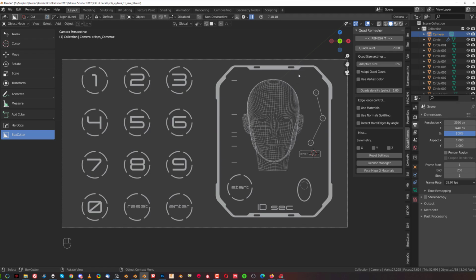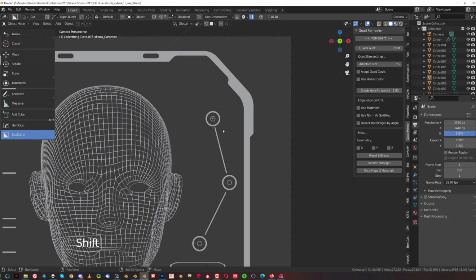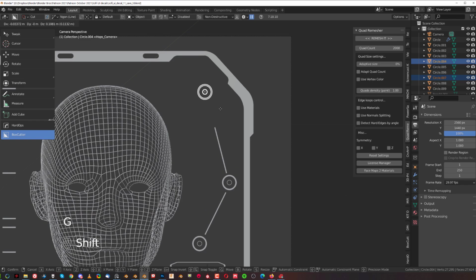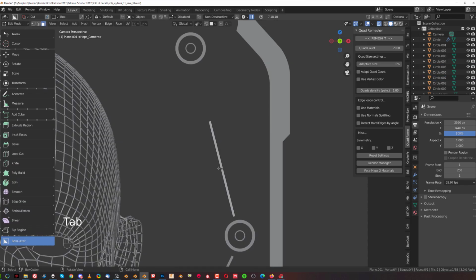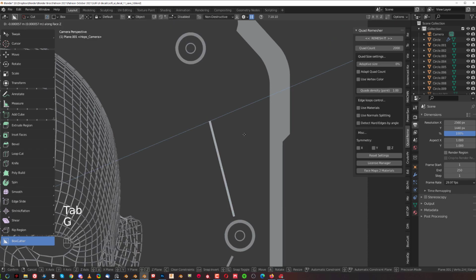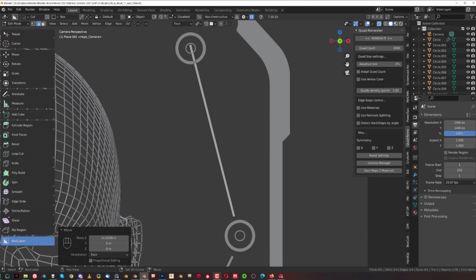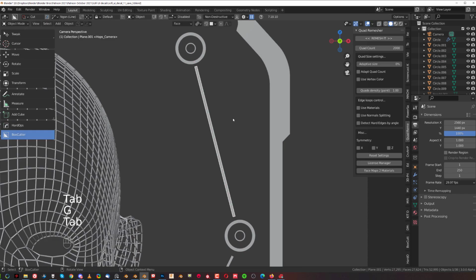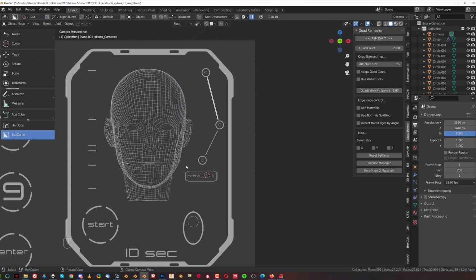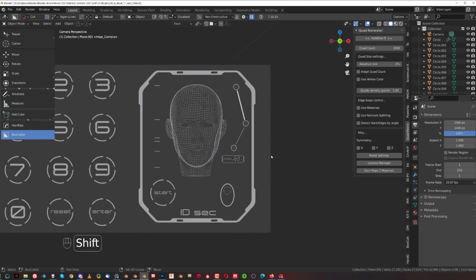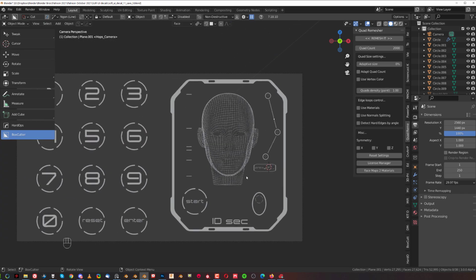I could probably use something here as well on the top. I can see that there's a bit of a space here. We could use something over there to balance off this side. What I could do is move this one a little bit higher, right? Click on this face, set the custom orientation, select this edge and GZ or GY, GX, there we go, and move it here on this orientation. GX, there we go. So it's going to be going from the top of the head here, boom, down to the lips. That's kind of cool, I like that. Cool, so it covers this area here a bit better.